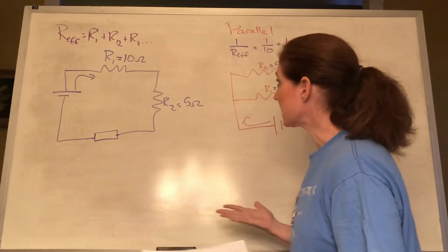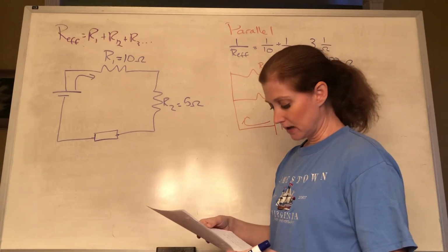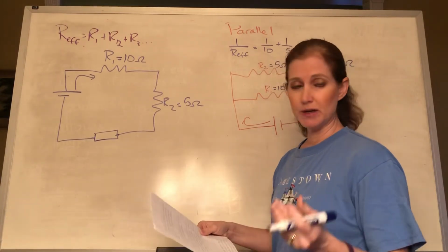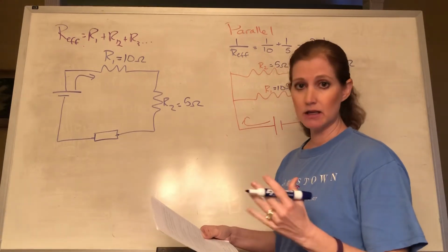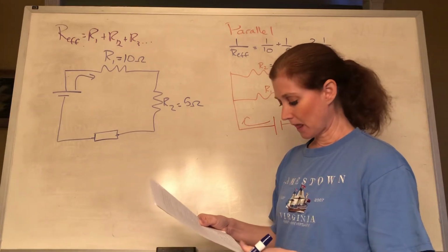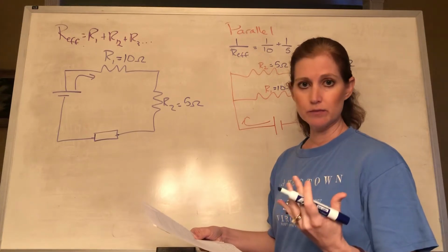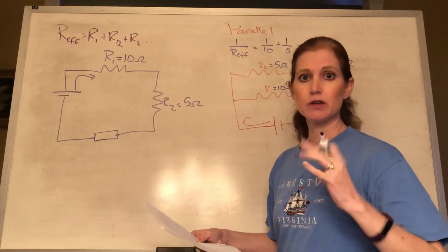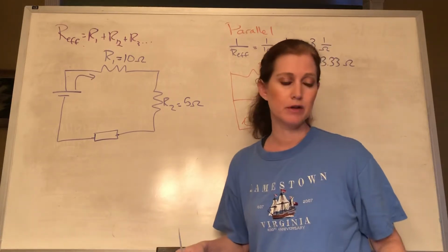Circuit breakers do the same thing. You've got those in your house, and it's made of material that bends as it heats up, and so the hotter it gets, the more it's going to bend, and then when it gets to a certain point that's predetermined, then the circuit will flip and shut everything off to stop the current from flowing.